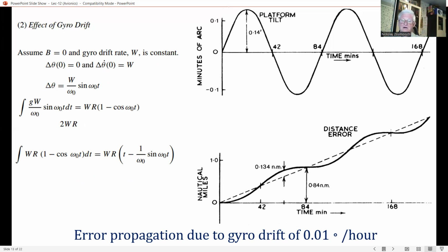Such sensor errors would produce vertical errors of 4.2 minutes of arc and 2 minutes of arc respectively, and the resulting standalone vertical accuracy would be around 0.1 degree.